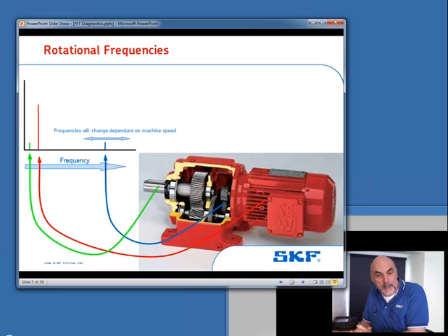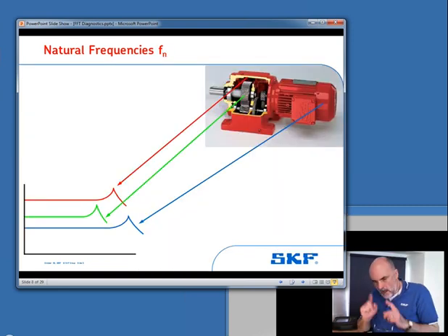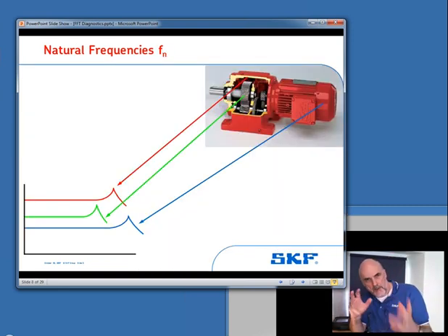And there's a webinar dedicated to variable speed machinery analysis, and we would use techniques such as waterfalls and colour spectrograms to make our diagnosis. An important note: when we're looking at the shape of the spectrum, we're looking at live spectra very shortly.